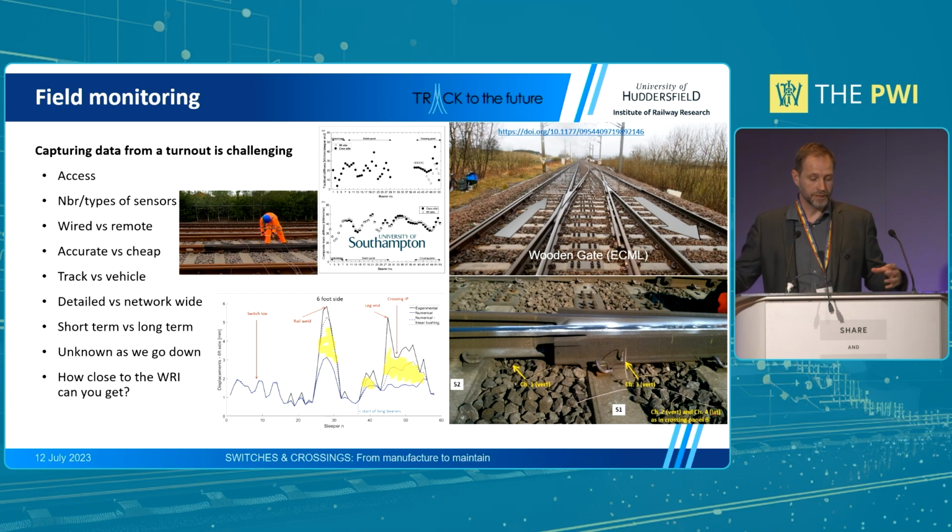But also transversely across the sleepers, we actually had to create a lot of voiding there to get the right results. So we know that transversely things are not smooth, not homogeneous, and the collars of the long bearers were also broken, evidently, where we had those voids. So as well as they work initially, they're not designed really to withstand the type of load and stresses they get on track.